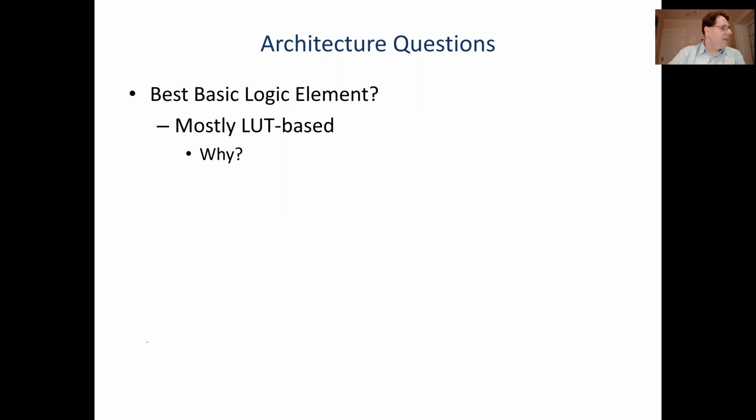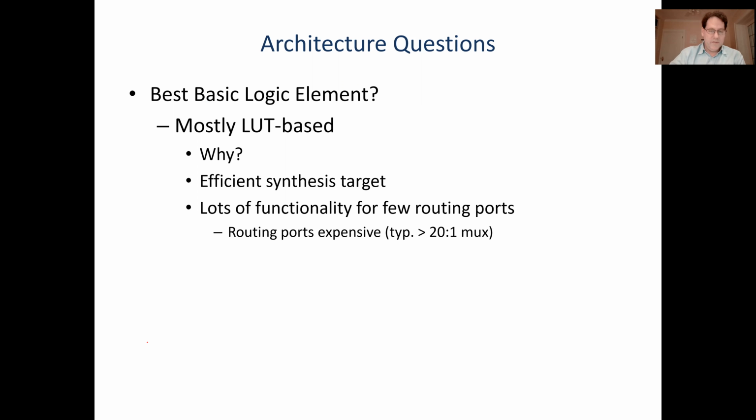Yeah, so they can implement any, as Edwin said, any K-input function. That's really the key to both of their advantages. They're an efficient synthesis target because it's easy to tell if something fits in a lookup table. If it has K or fewer inputs, it fits. So that's nice for your CAD tools.